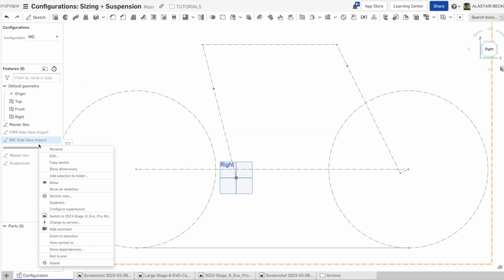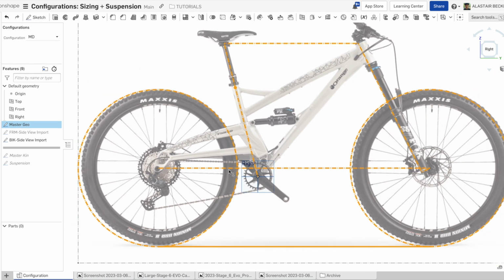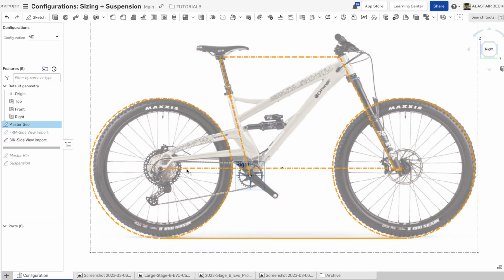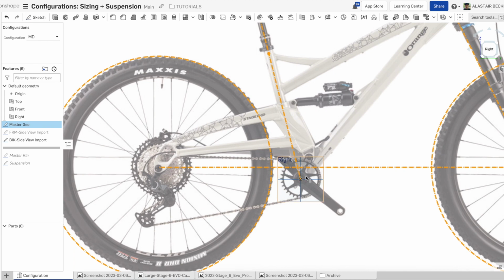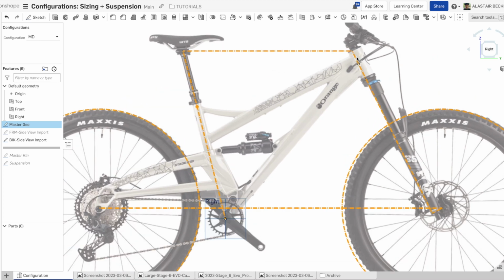The next thing I did was import an image of the complete bike, which we know should be a little bit more, not accurate, but it is the right bike. It has the right specifications. But the problem is, because it's a side-on photograph, you'll never get total accuracy on this. But straight away, you can see that the geometry starts to look slightly closer. We can overlay and move the image slightly, but it's impossible to get a true side view of a bike just with the way proportions work. But we've scaled this and moved it around and got it quite close. We want the BB to be hovering over our origin, and then we can see that our rear axle is not too far away and front axle is not too far away. Again, the head tube is a little bit forward of there.